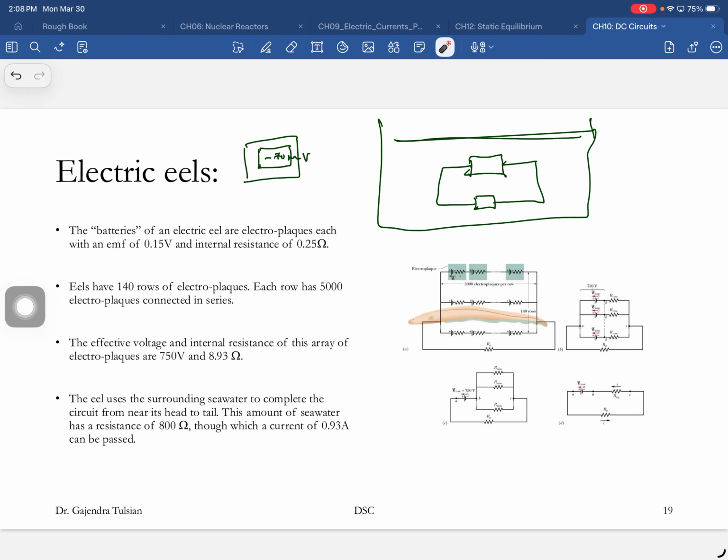You guys have all seen three-prong devices, and what the three prongs do is it's a safety feature. So you see, if you have an electrical instrument device like this, and let's say the wire breaks and is touching the casing, and then you're holding onto the casing, the current will pass through you to the ground, and that's not good for your health.